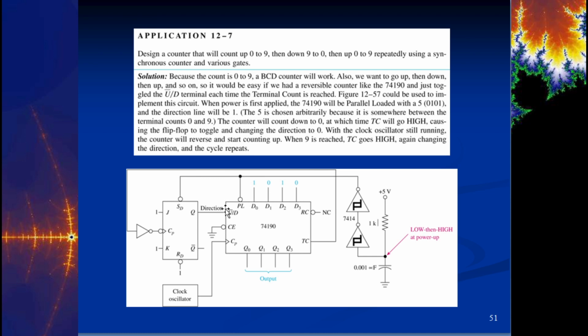So this is just going to change direction. It's going to stay where it's at, and then it's going to count down, right? The Q output is still at 9 because we have flip-flops in here that didn't just automatically change states. Those Qs are still wherever they were before. So now we just change direction and go opposite.